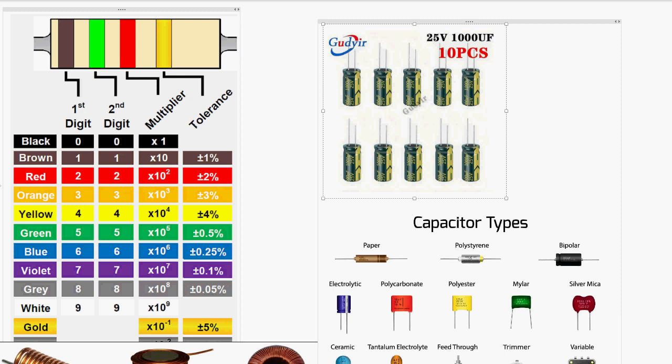Okay, now there is one more line that shows the quality of the resistor, and if it's gold, the variability is 5%. If it's silver, it's 10%. Most likely they select during manufacturing, take the gold out, sell at a little bit higher price, and the remaining they mark silver. So remember this color code.